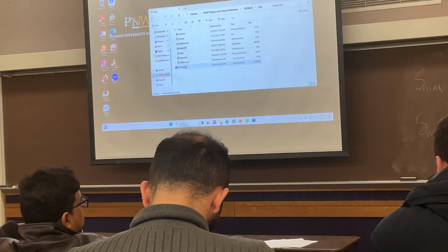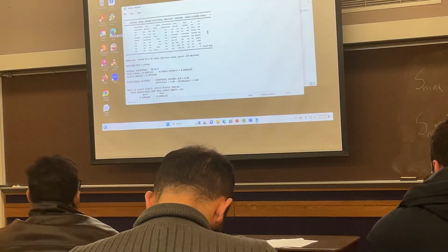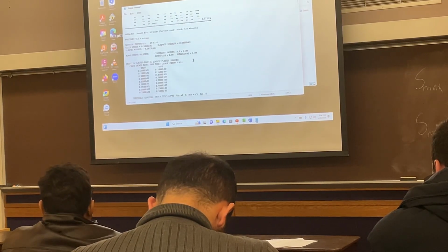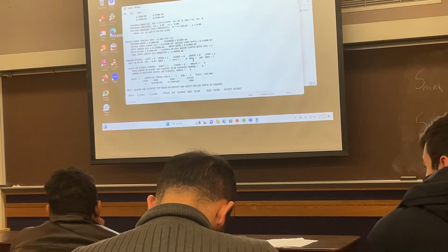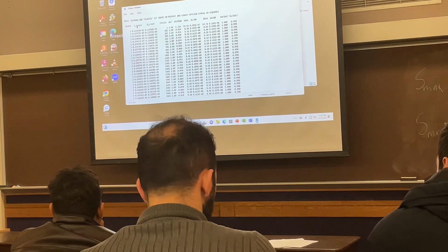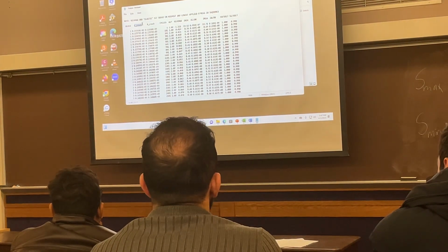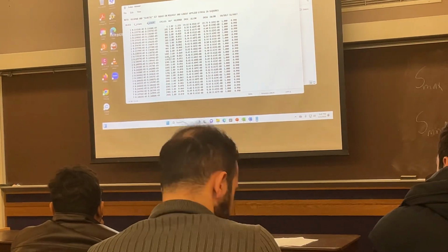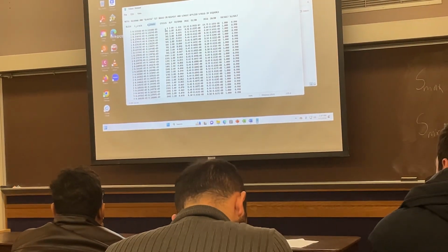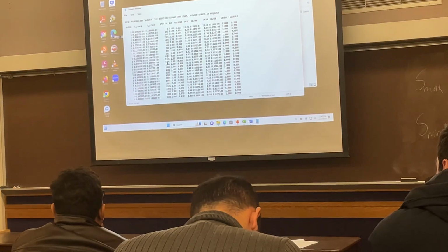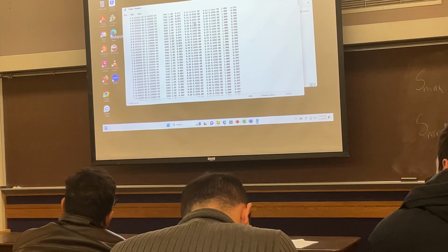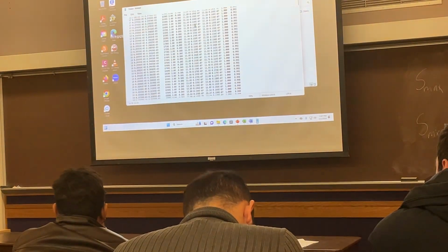So just the output file. It's something like this when you open it. For all those initial conditions, 9 of them, there's a description that gave you the crack size. Cycle by cycle, it gives you the crack size in C direction and A direction for each of the cycles. So the cycles that you see in the report are not necessarily 1, 2, not from 1 to 100, 200, and 1000. And also the rate is basically the crack growth rate.